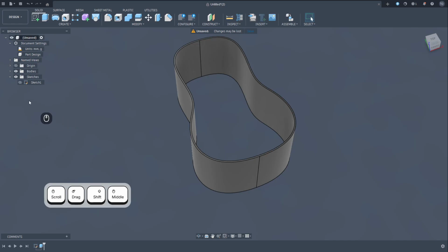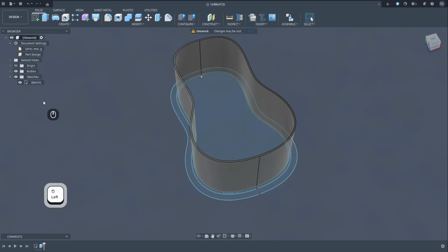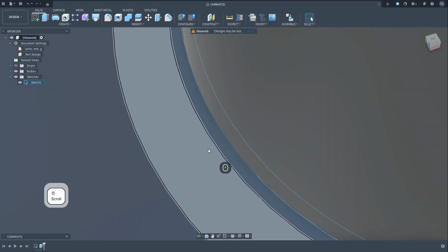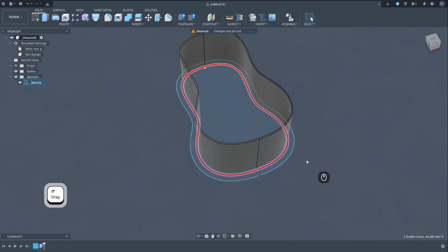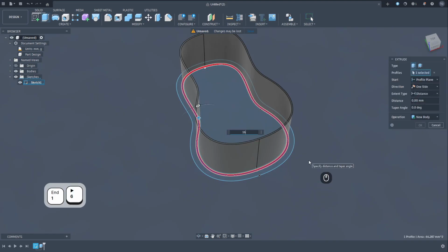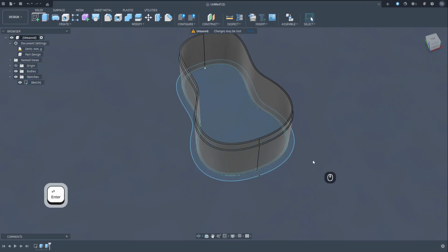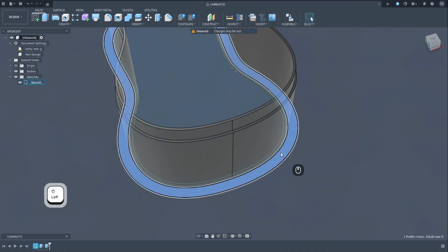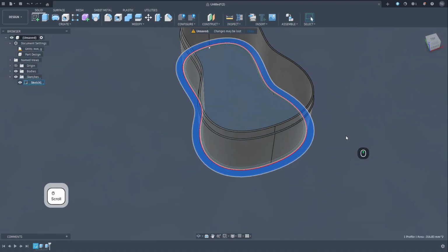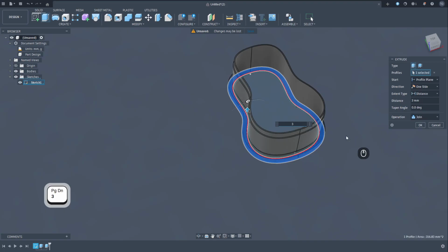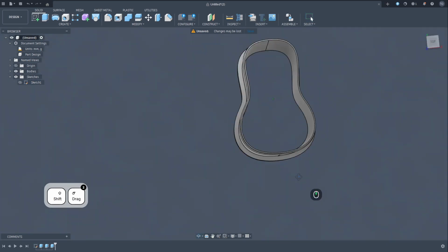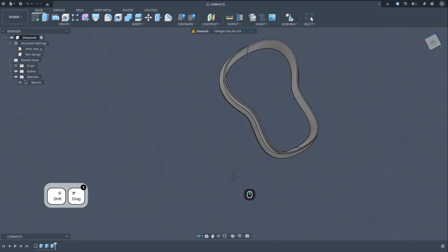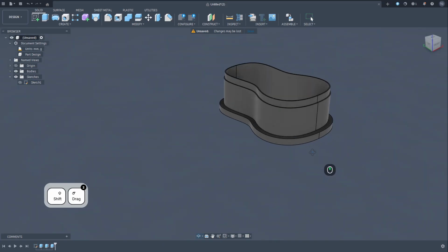So I'm just gonna make my sketch visible again and go back to the second line, and I'm gonna select the second profile that I've created in my sketch. I'm gonna extrude this by 60 millimeters to give myself a reinforcement wall, and I'm gonna select this third profile and I'm gonna extrude this by 3 millimeters to give myself something to hold on to. So that's my first clay cutter done on a very strange looking profile.